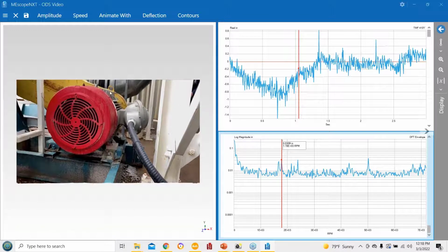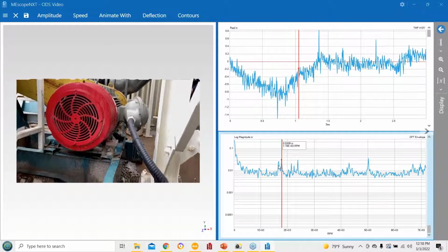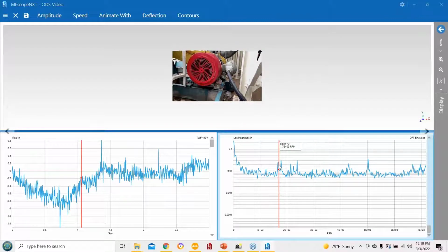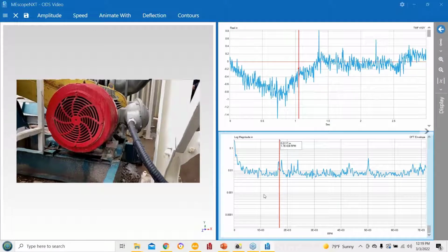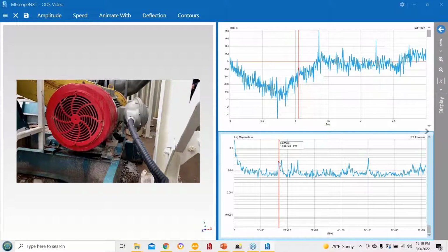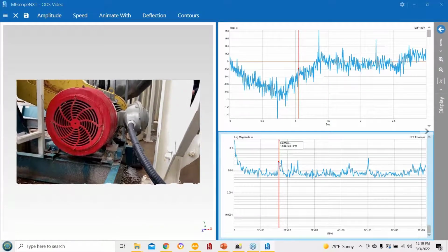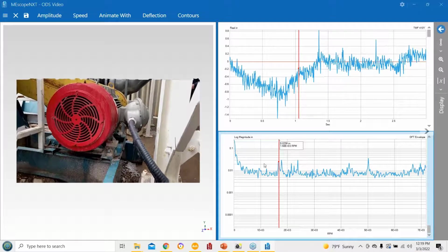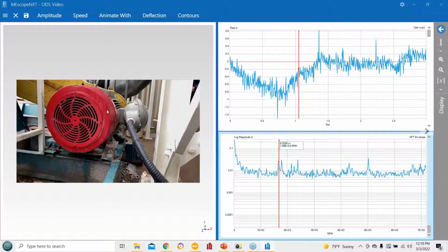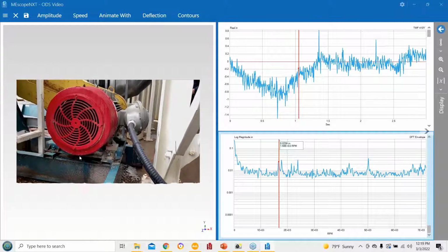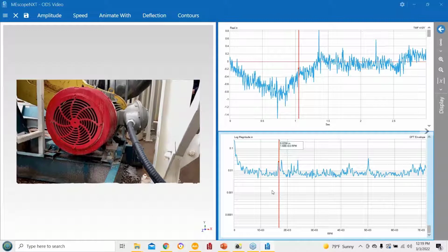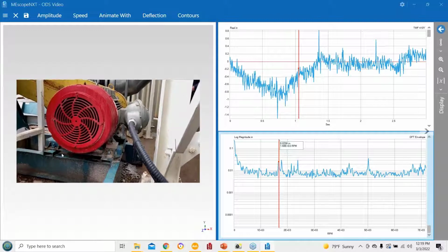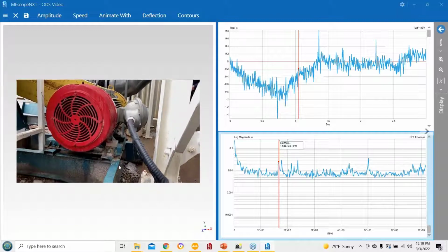Everything's going up and down. I still need to remove the background and get rid of that, but this is the one that's more interesting to me. Sorry about that. This is interesting because of the twist in the motor. So it could be coming from too tight of a belt, or an eccentric pulley, something like that, or it's just the frame is pitching as it's bouncing. And we definitely would need another view to see what's going on in here.